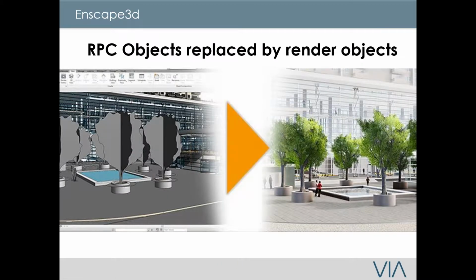The nicest thing about Enscape is that it actually takes your RPCs. So if you have an RPC inside Revit, it will automatically generate into a tree. RPC, what is it called? I don't remember. It's something to do with flat images. In SketchUp, when you insert any people and rotate them, that object will rotate with it. It's similar to how it does it inside Revit.